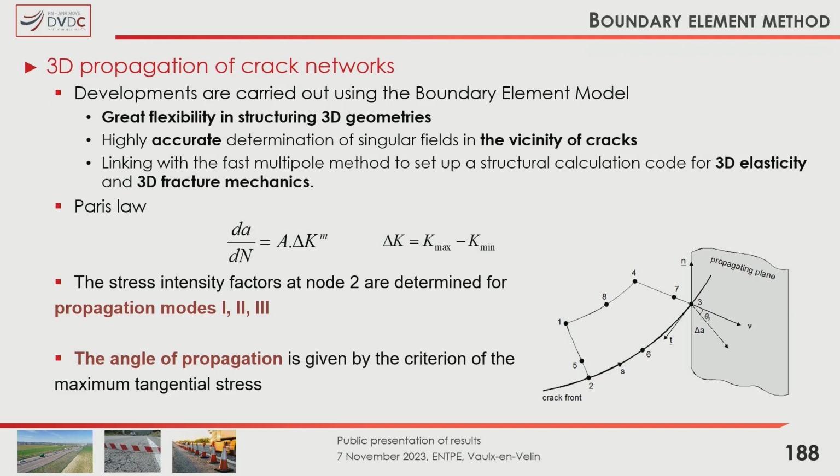It seemed more appropriate because it looked at the various cracks, which are treated as discontinuities in a geometrical sense. So I have a 3-dimensional grid of the cracks and their spread, and this means that we can go a lot faster and gain a great deal of accuracy for the various cracks, so that there are fewer finite elements. We looked at this in 3D elasticity and 3D fracture mechanics.